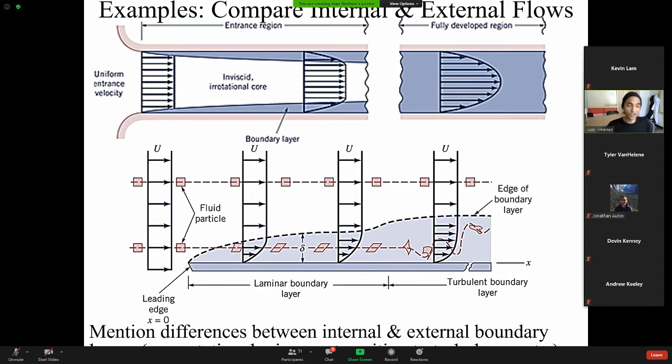Zachary Jordan, what's the gradient? What's the value of the gradient, the velocity gradient of a uniform flow field? It would just be 0, right? Absolutely. So this is very important. So then if you have 0 velocity gradient, what does that mean in terms of angular velocity? There isn't, or it's 0 too. Yeah, so then you have an irrotational flow.